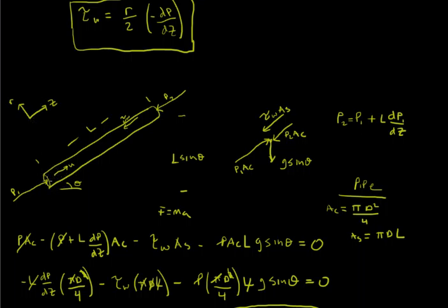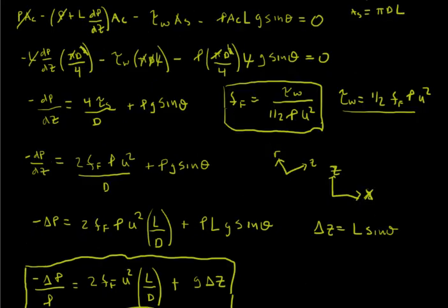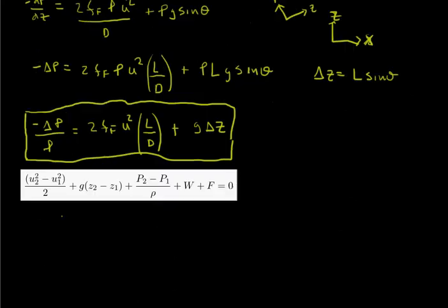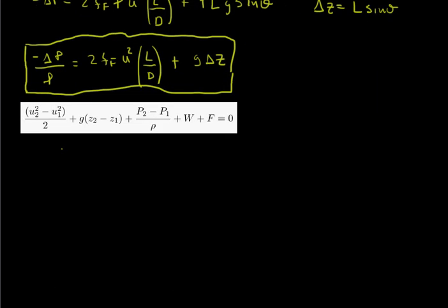I just want you to notice that the velocity of the fluid is not going to change. At our point 1 here, the average fluid velocity is going to remain constant all through here. I'm bringing that up so that we can see why I'm crossing out this kinetic energy term in the mechanical energy balance.